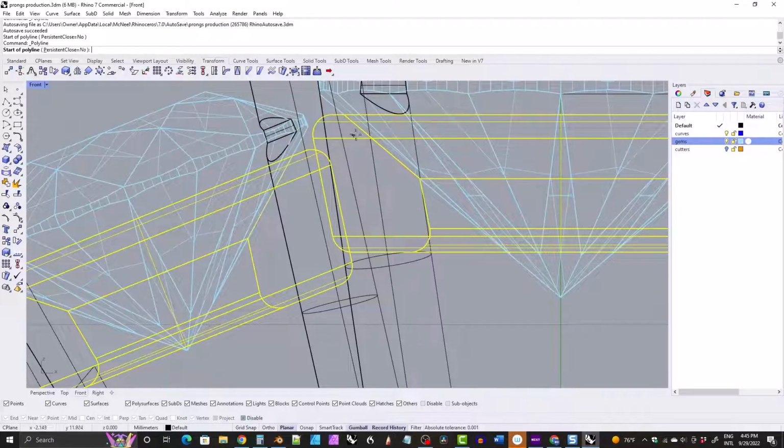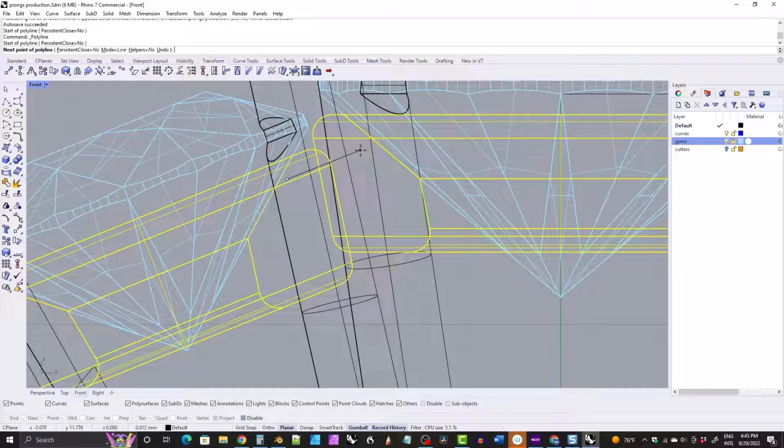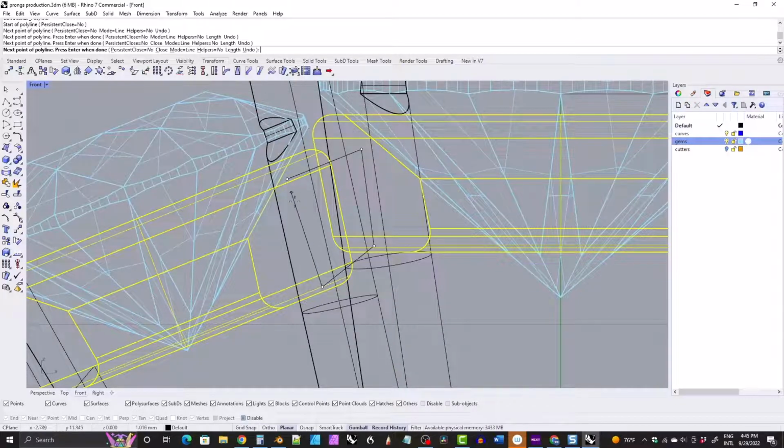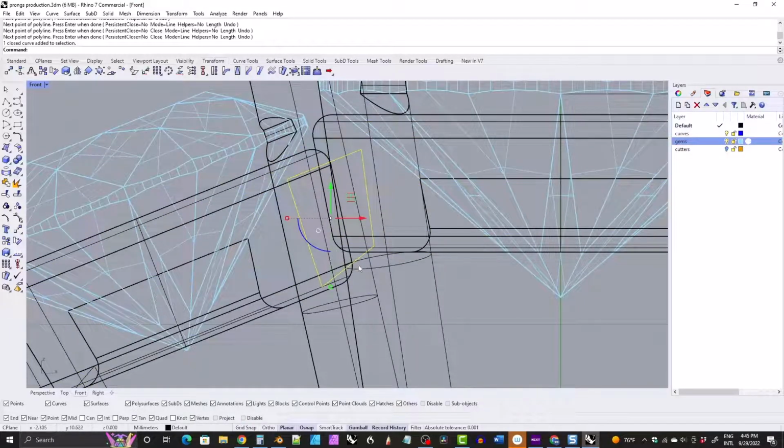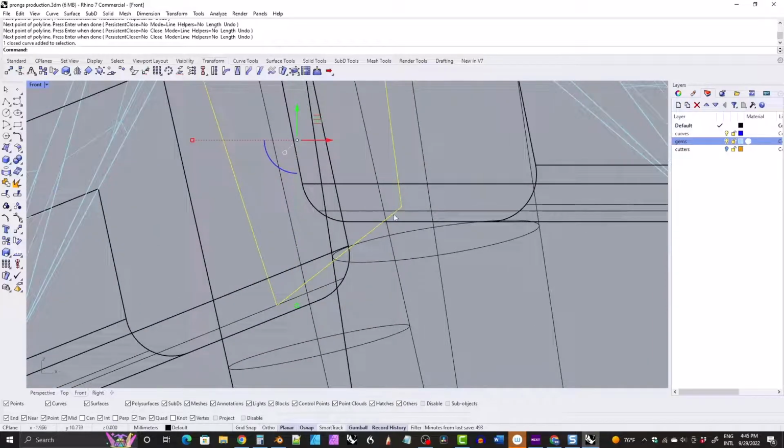Keeping in your angle with this side gallery rail here, maybe come like about here, and starting over in the side gallery rail, go across over into the middle gallery rail, and then come down where you're still inside this gallery rail, and then just cross over here, staying again inside this gallery rail, and then turn O-snaps back on and close off this shape here. So we're just making kind of a little bridge here between these two shapes.